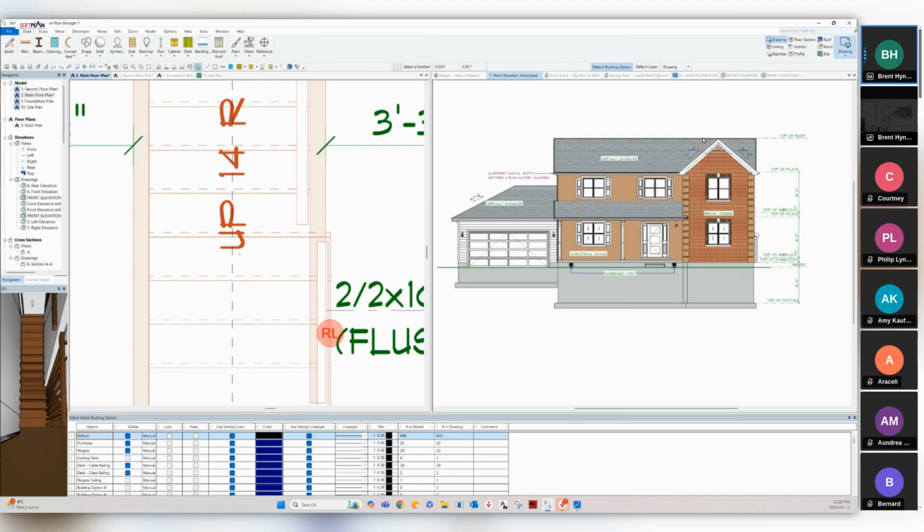If we don't find one, don't fret. If putting the site plan in isn't ready or it's not something you do, we're going to use the offset that is already defined with your auto horizon in 3D. When you go into 3D, the auto horizon appears, and in your options, you can set where that is located relative to the underside of the sill plate or the top of your foundation. So if that's 6 inches down, that's the number we're going to use.